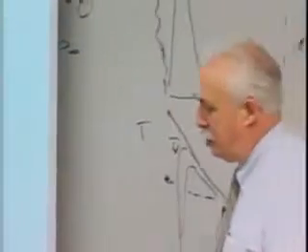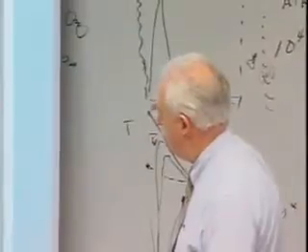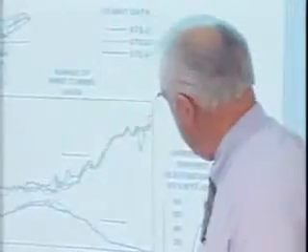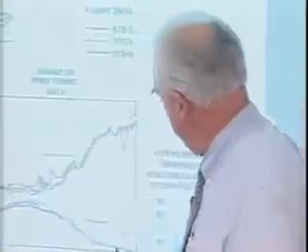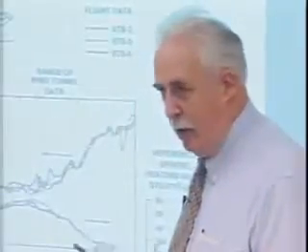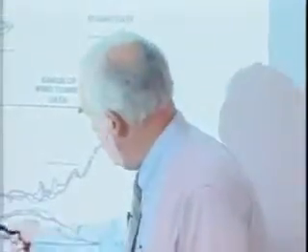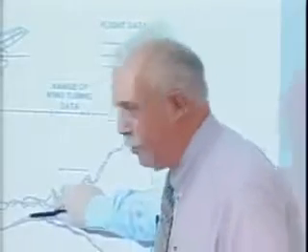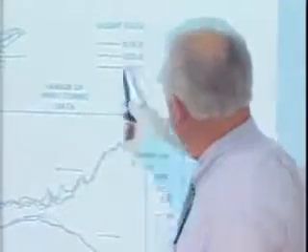Okay, now I think the next one is probably the thermal protection system. No, one more measurement. This is the lee side. This is normal shock versus heat transfer, film heat transfer coefficient, basically heat transfer, log. This is the heating shown here as a function of normal shock Reynolds number. Now remember I said we designed the trajectories, so we went up here and spent 10 minutes and then came down as a normal shock Reynolds number. And here are 3 trajectories with the heating on one location on the lee side.